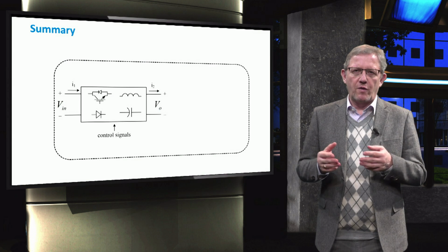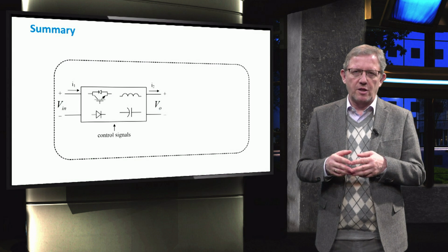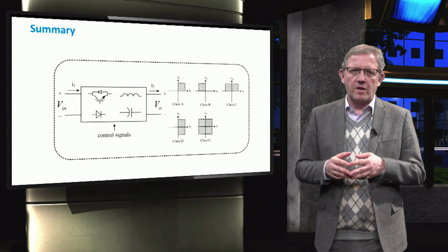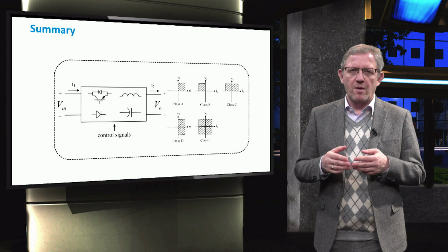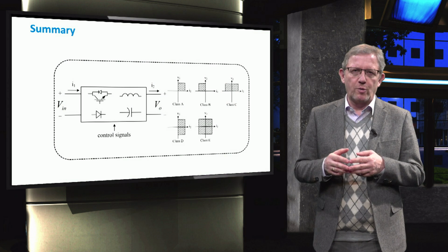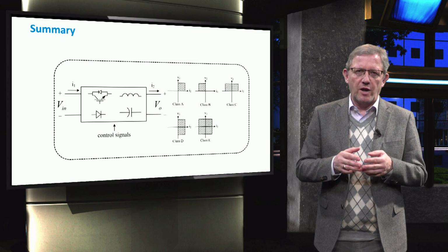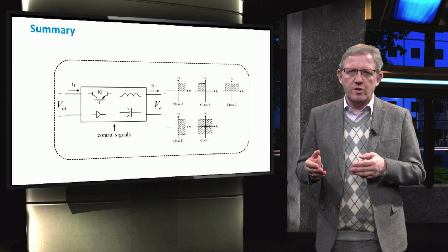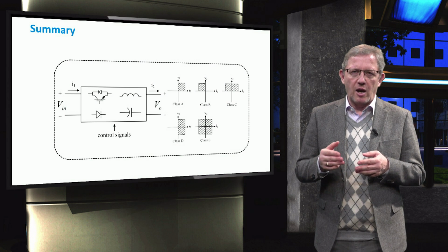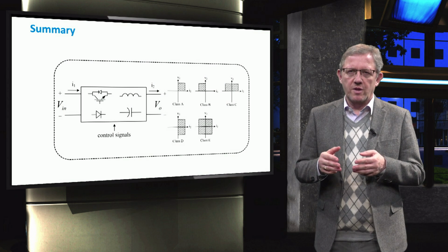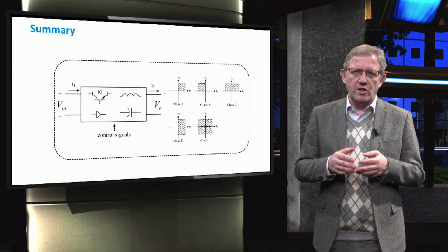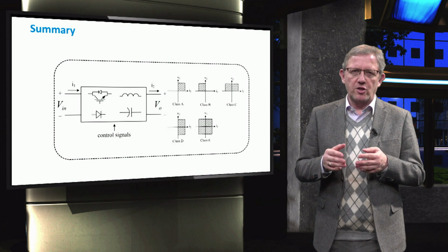In this video, we first reviewed the main elements of DC-DC converters. Then, we introduced 5 different classes of DC-DC converters, mainly based on the polarity of output voltage and the direction of the output currents. Boost or buck converters can allow the unidirectional flow of power, while buck and boost, full bridge and dual-active bridge are able to facilitate bidirectional power flows.